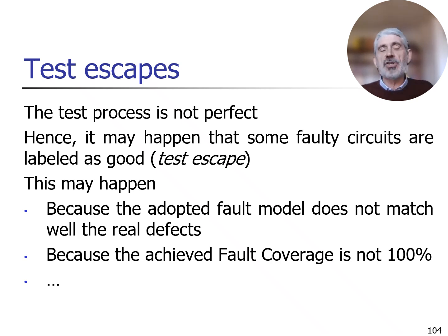It is not always the case that the fault model we choose, for example, the stuck-at fault, is suitable enough to manage all possible defects. More complex fault models may be required. Also, for cost and economic purposes, perhaps I decide not to achieve 100% full coverage because the test would be too long and the test cost too high.